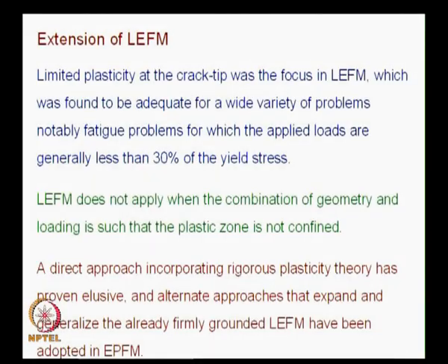So, there is similarity between what you have done in LEFM. There you had fracture toughness, K1C has to be determined. Similarly, here you will find out J1C has to be determined. So, there is parallelism in this, but you need to go through certain approximations. So, before we get into elastoplastic fracture mechanics, we will try to understand what is J integral. That is the way that we are going to proceed.